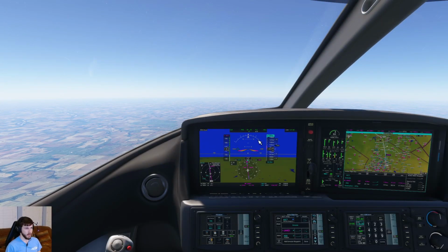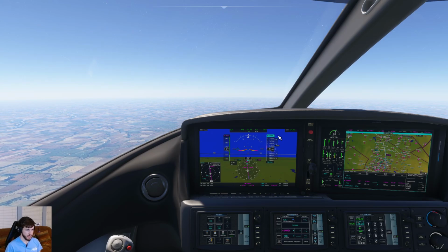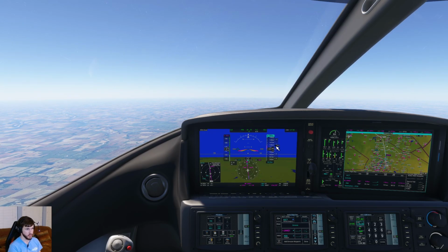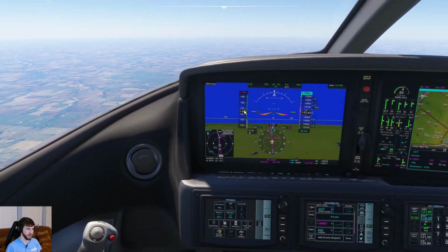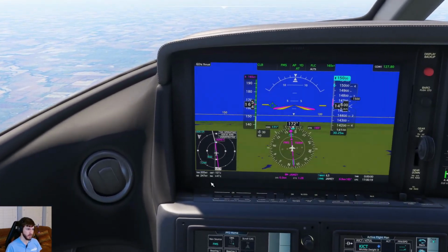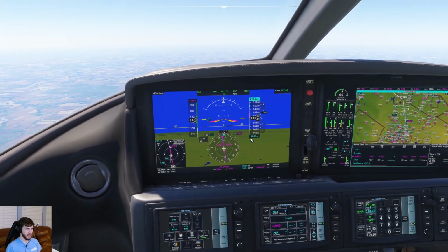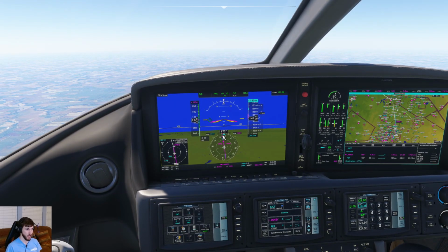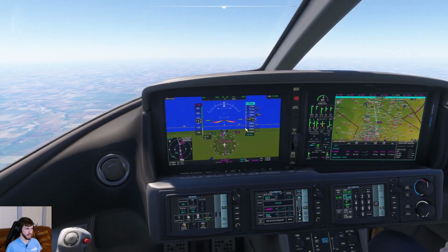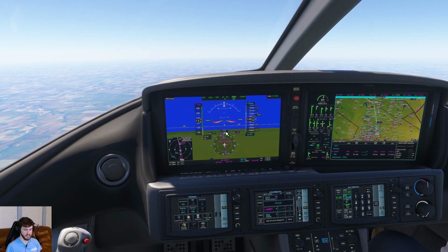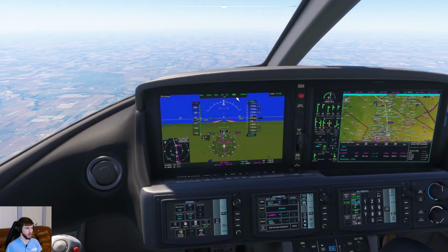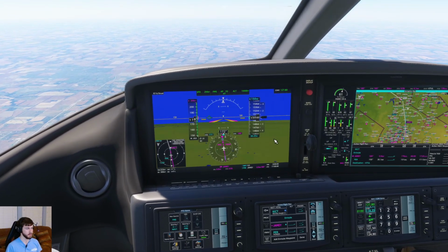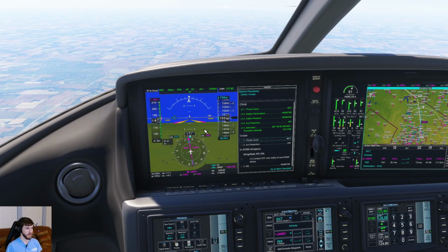All right, we just heard our 1 to go alert, which is 1,000 feet to go to our selected altitude. So we'll be leveling off very shortly. And as you can see, we got a really big tailwind helping us out, which is pretty nice, especially when we are this down low, because at these lower altitudes, these airplanes are not as fast as they are when they're up higher. So it's nice having a push. So there's altitude hold, leveled off at 15,000, and we're gonna knock out our cruise checklist.